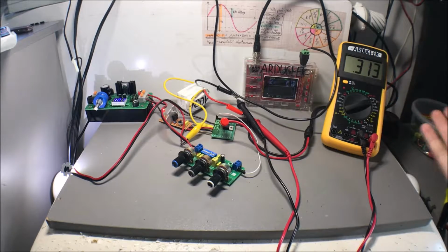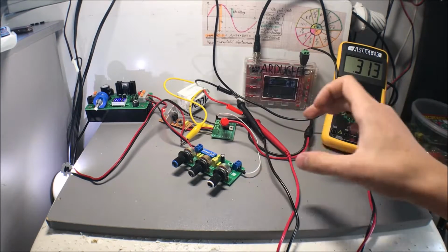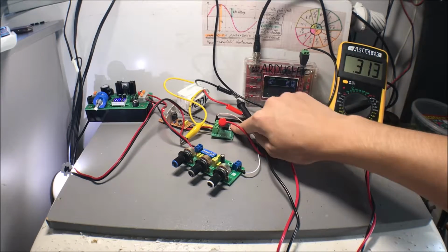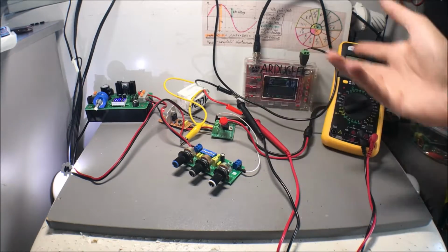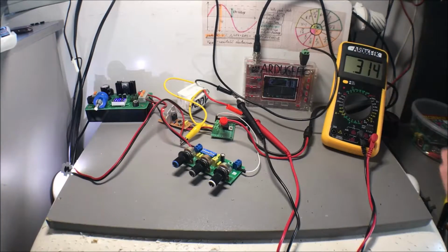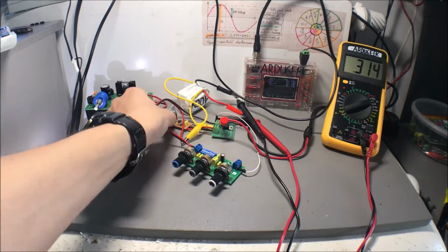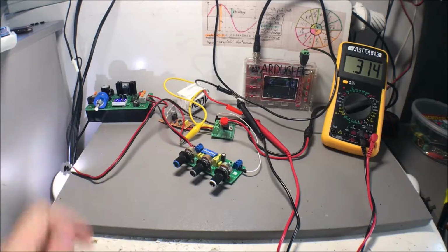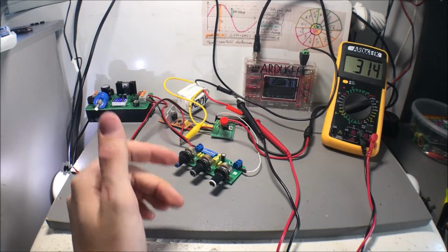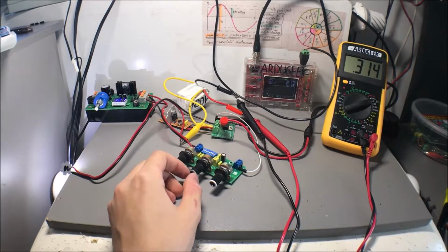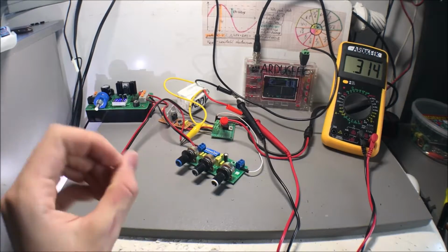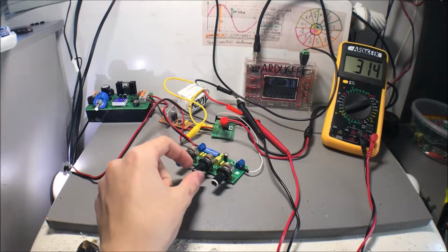And the second purpose with this current limiting converter is that I will not heat up the MOSFET. So only advantages, you may ask. No, because the LM317 constant current source is just heating up, the IC itself heats up. But besides that, we limit the current, and it is good in this case.